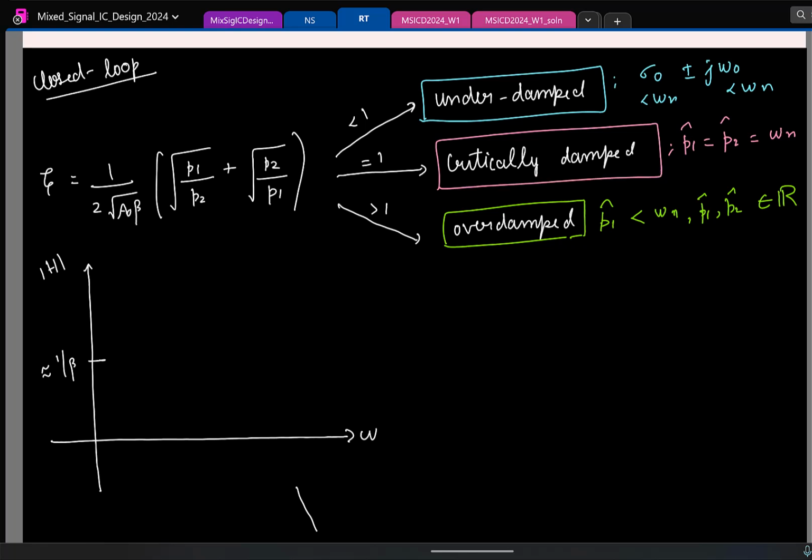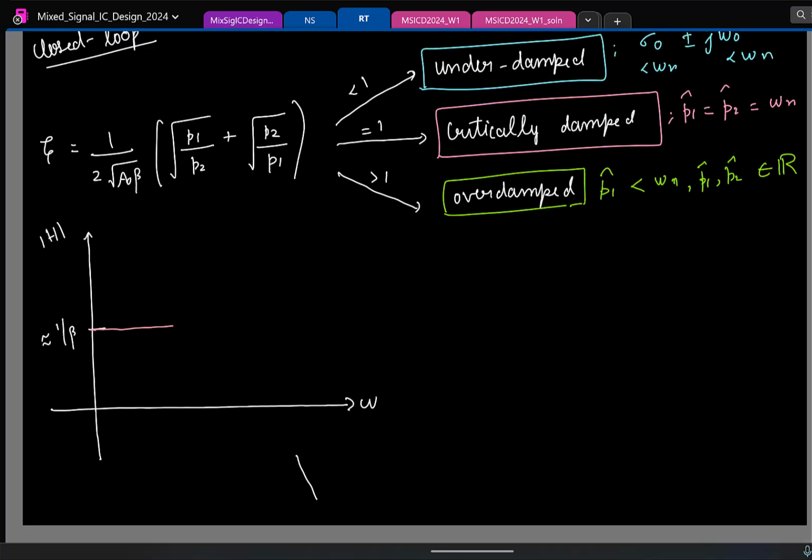So the closed loop poles, what can you say about them? They are exactly on the same location. So if I plot this, it's going to be flat till it hits both the closed loop poles. So here is where, let us say, omega n is. At this point is where you have both the poles. So at what slope will the magnitude plot drop by? Minus 40 dB per decade. Let me see if I can match this line. No, I can't. Okay.